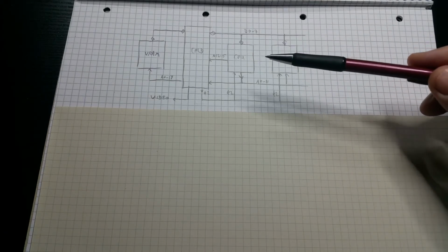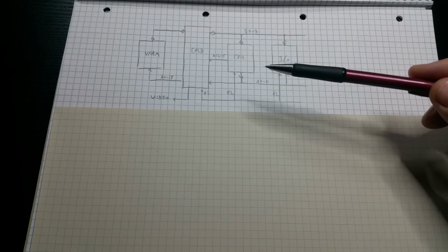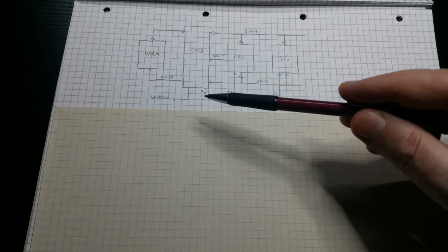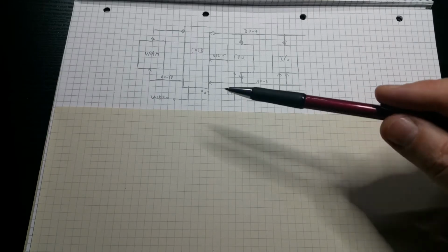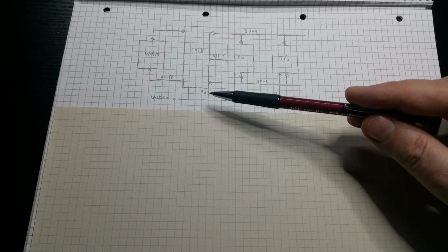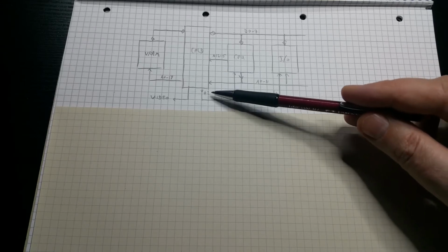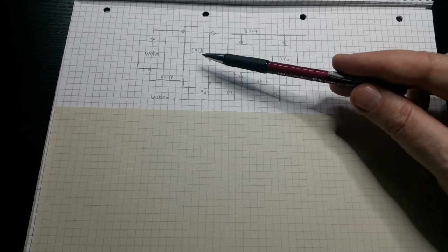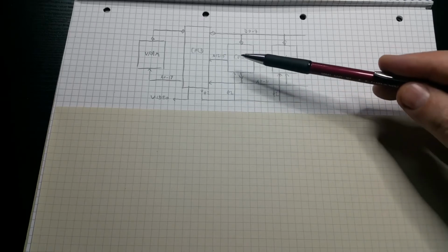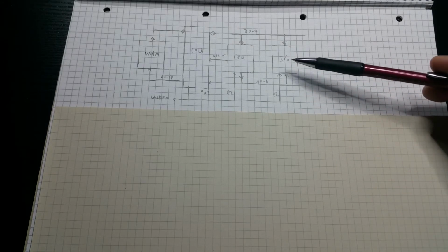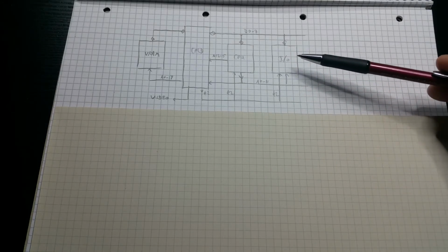What I haven't shown in the previous diagram was that there also are some control lines, of which I've shown only one in this diagram. The one that's most important is the clock signal, phi 2. This is created by the CPLD, and it's fed into the CPU as a system clock, and it's also fed into the I/O.